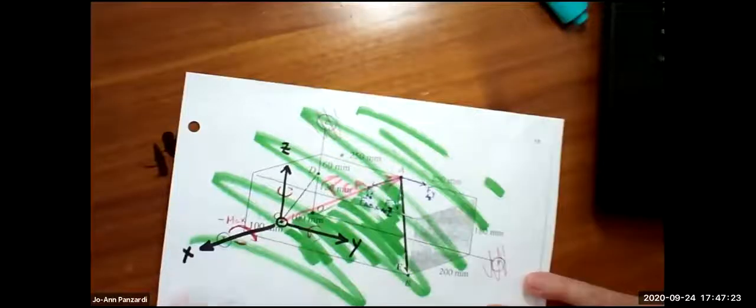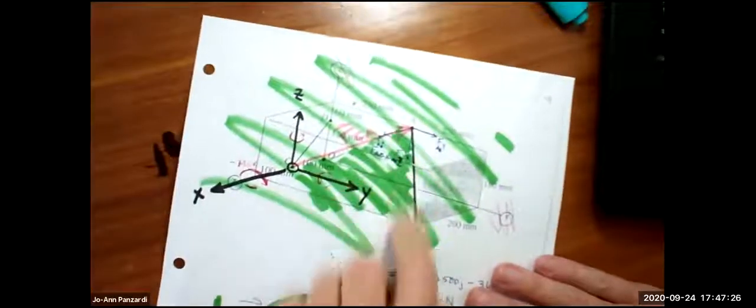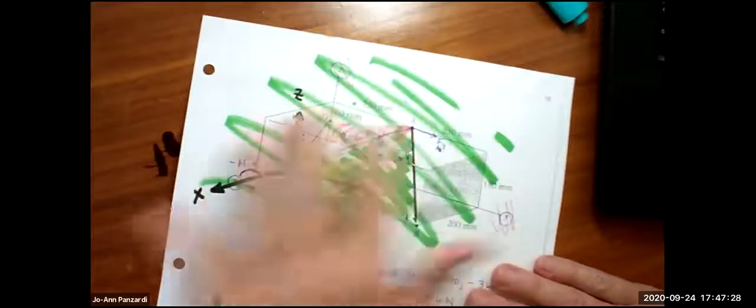So when you were holding up the safety pin, yes, it needed to start at C, right? It needed to be touching C and then pointing in that kind of back direction, right? Yes, and the reason why is because we were calculating the moment about point C. We didn't have to. We could have found the moment about point O or about point D. This force creates a moment about every point in here.